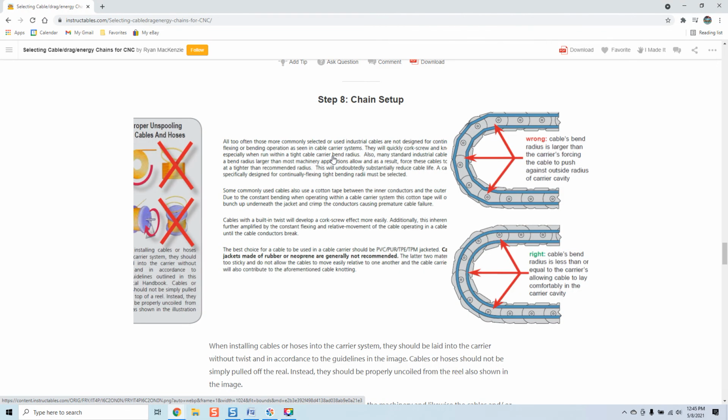And it's interesting how cables behave, because a lot of guys don't realize that even if the cable's in the chain by itself, the cable, as it moves fore and aft on the x-axis, actually moves slightly outside the actual chain. So where the cable exits the chain, you will see that the cable is constantly in movement. It's very minimal if the appropriate size cable is used, but it is still present.